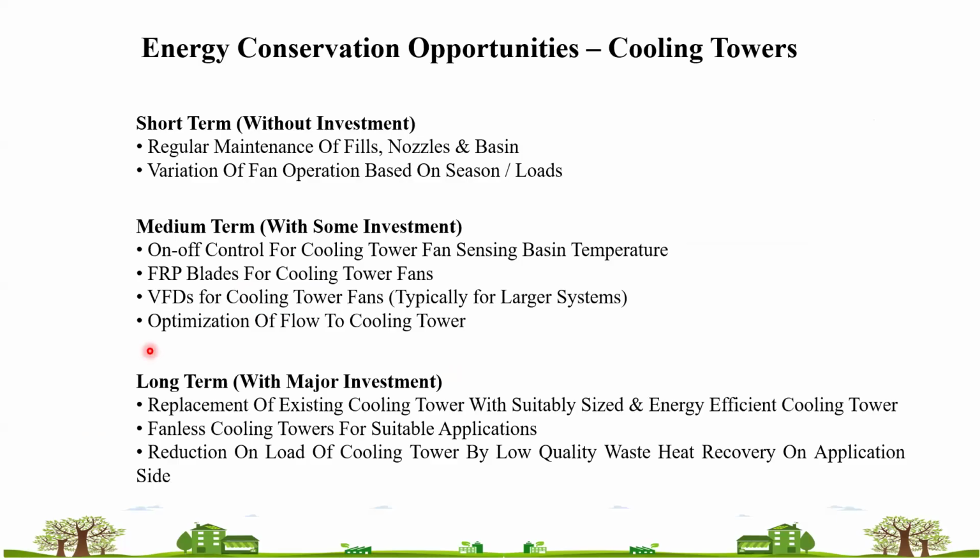Then this is the third part, when you move to the energy conservation opportunities in the cooling tower. There are short-term investments: you can conduct regular maintenance of the fill, nozzle and basin. It's a preventive or regular maintenance practice. Then variation of fan operation based on seasons and loads. You can adjust the angles, which is only a mechanical change in the blade angle.